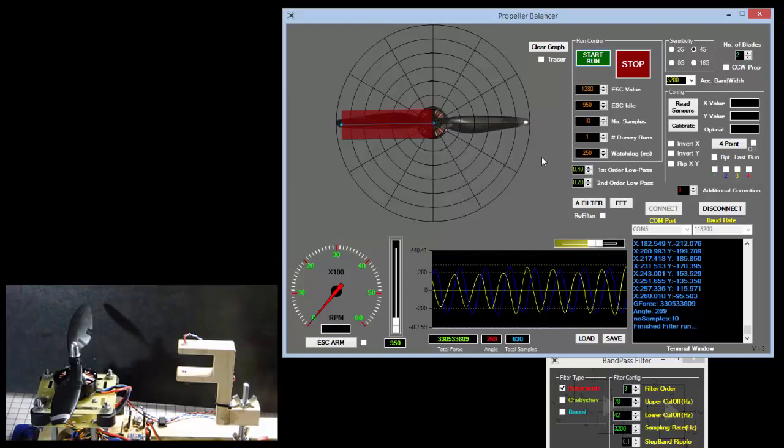All we need is force magnitude. So it's always good to leave the filters in here, because the more filtering we do, the more components we take away. For a 4-point balance, we want everything there, because all we're looking for is a magnitude, not a direction. So those will remain, but for balancing the blade, you can begin to see what improvement the filters make.